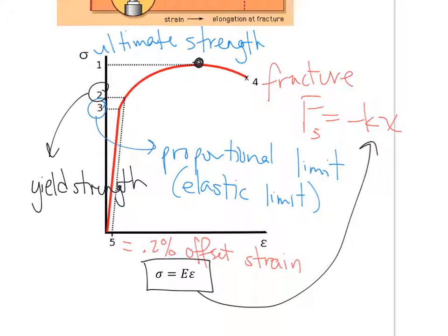If you draw a line parallel to this region here, this is the location that indicates the yield stress. This is where the actual material enters what we call the plastic range, where it really begins to stretch a lot. That's the mathematical way of locating that location. Is it only 0.2%? Yeah, the traditional one is 0.2% off yield. It's just been like the accepted rate.